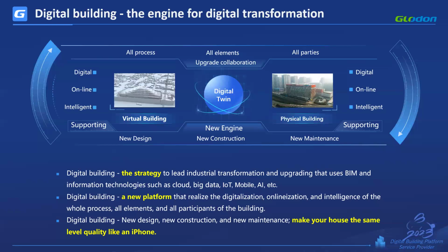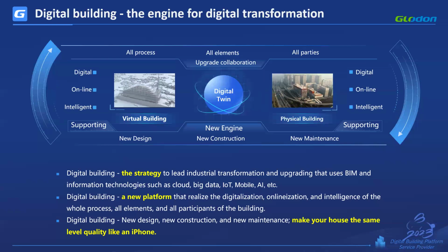What is the best example? It is e-tendering. So you can do virtual pre-construction. Then you can create the 3D model and simulate that model. You can connect your model with your construction program, and then you can simulate that project, by using software like Navisworks, Power Manager, or Synchro Pro. So this is your virtual building. You can make important decisions with regard to physical buildings by using this digital replica, this virtual building.